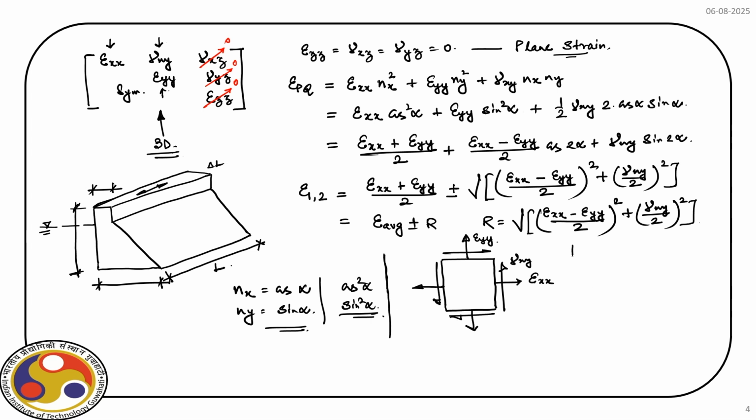And for that, if you recall, we have the Mohr circle. We can easily draw the Mohr circle, with epsilon ii and epsilon ij axes. So, if we have say 2 points, then we can draw the Mohr circle, and these are the principal strains and the maximum shear strain we can find out.